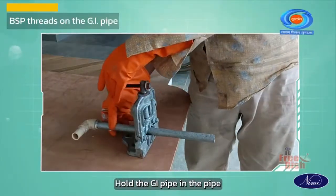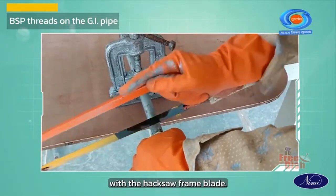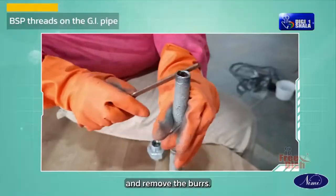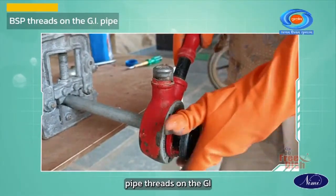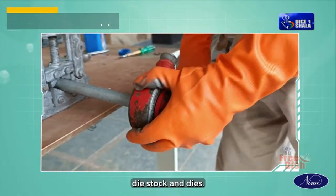Hold the GI pipe in the pipe vise and cut the bits to the required size with the hacksaw frame blade. File the edges with a flat file and remove the burrs. Select BSP or British Standard pipe threads on the GI pipe bits using the BSP die stock and dies.